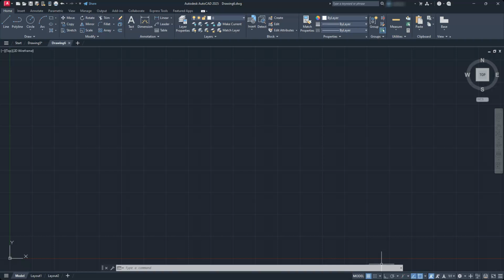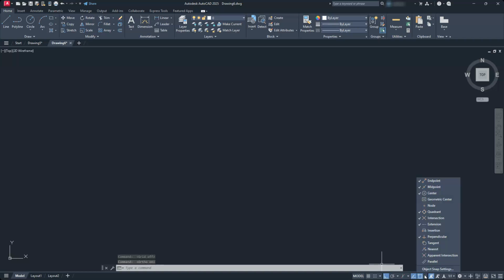You can set this up, and I will set that up in a later video showing you how to set up some things in AutoCAD. There are some things that you can just set up and say, hey, I'm tired of turning off my grid every time I come to a video, and then having to turn my ortho on, and set some of these certain things. If you want to be a little bit proactive about that, go ahead and search for templates. It's called a DWT file, right?